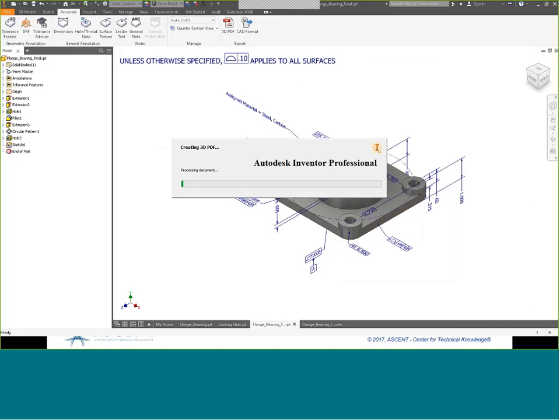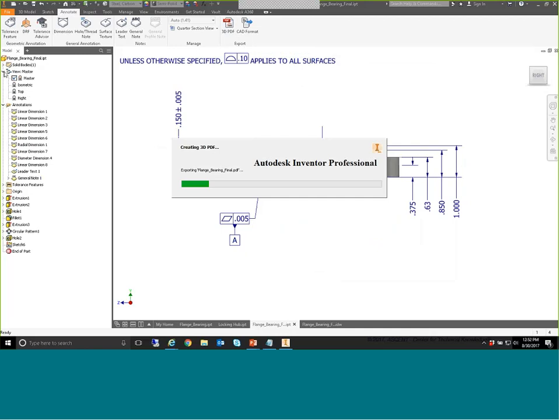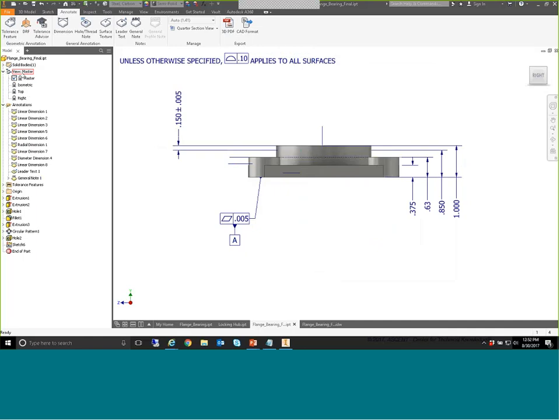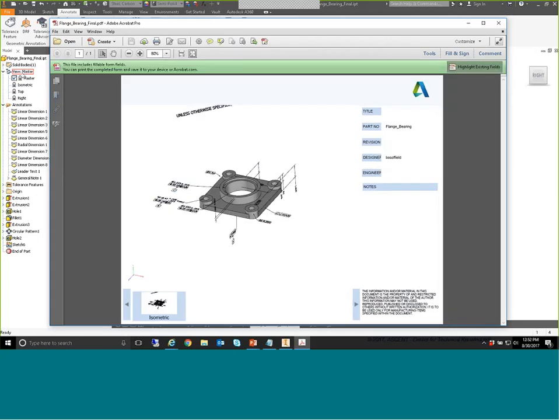When it talked about design views, this is just like in standard part design. You have the ability to create design views of your annotations. You can customize the way they're laid out, how they display, and how they're oriented, that type of thing. I didn't get into that in this course because I just don't have enough time in 1 hour. That is something that's covered in a whole chapter in our training guide. So if you're looking at sharing with a PDF format, you'll definitely want to look at learning how to do that. And you can see now I have my 3D PDF.